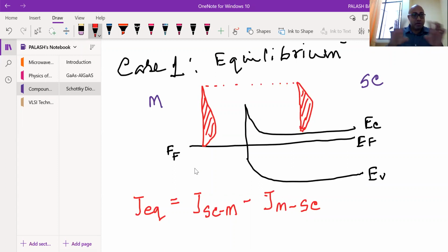Take a PN junction diode. When you try to see the amount of current flowing from P type to N type or N type to P type without giving any voltage, you see it is almost zero. Why is it zero? It doesn't mean that it is always zero. In the N-type semiconductor, plenty of carriers are there and they are actually moving.